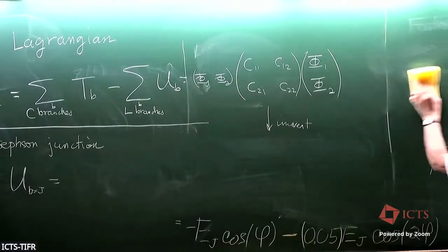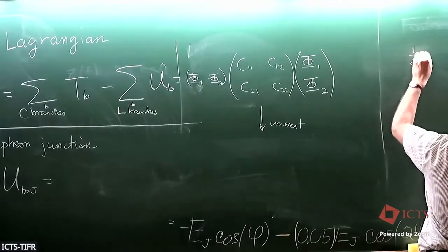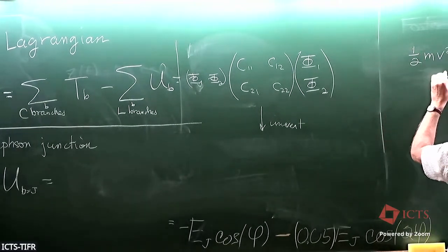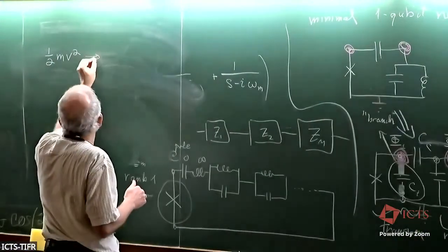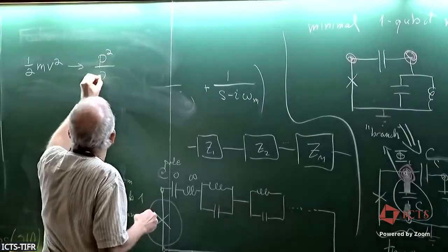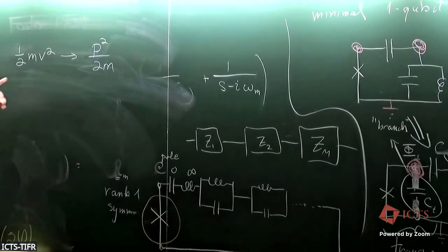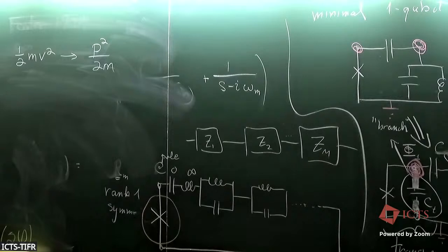Remember, your basic kinetic energy, you on the one hand write it as 1/2 mv squared, (dx/dt) squared, or you write it as p squared over 2m. So there's the inversion. Mass goes downstairs when you write things in terms of the canonical momentum. For us, the canonical momentum is this charge operator, which I've otherwise been neglecting, but it comes back when you do the Legendre transformation. And you have to invert, and it's not a simple scalar inversion. You have to invert this as a matrix.